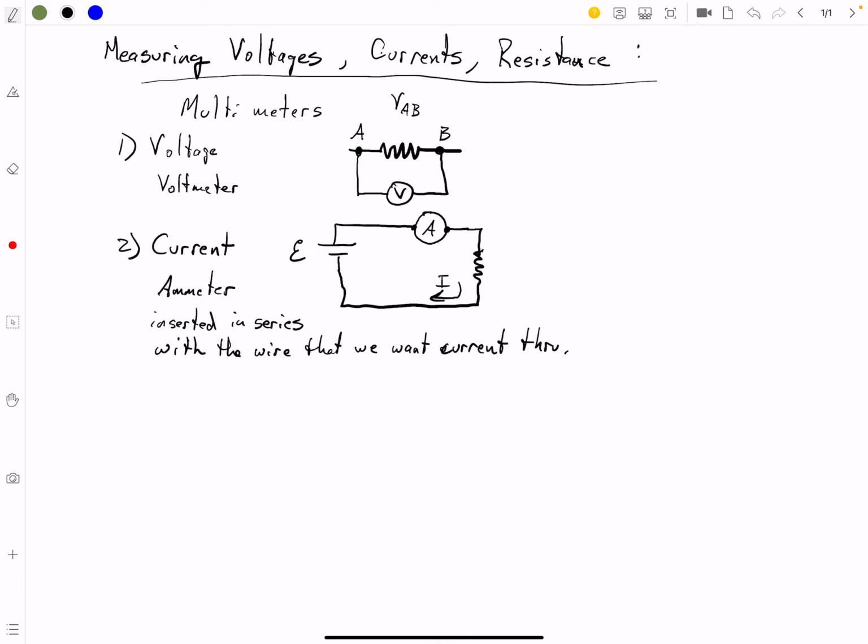We want resistance now. We want to measure the resistance. Of course, you have to switch your voltmeter, your multimeter. You got to switch from voltages to currents. And you got to do it right? You got to select the right scale and everything. Otherwise, you might in the future fry your multimeter because you don't have the right selection. Digital multimeters will fry easier than the old galvanometers, which is what I still use actually because I tend to fry multimeters.